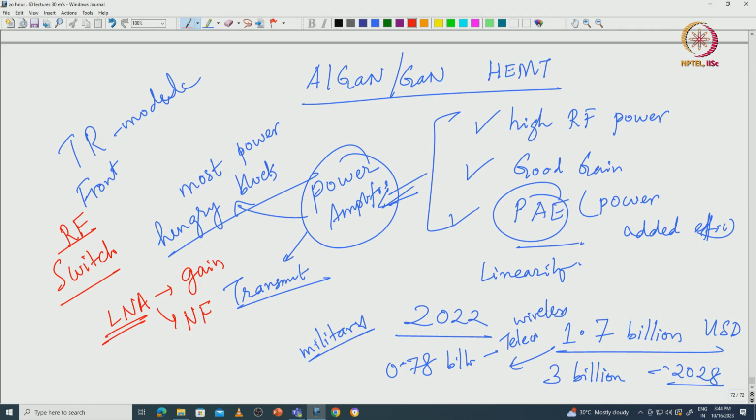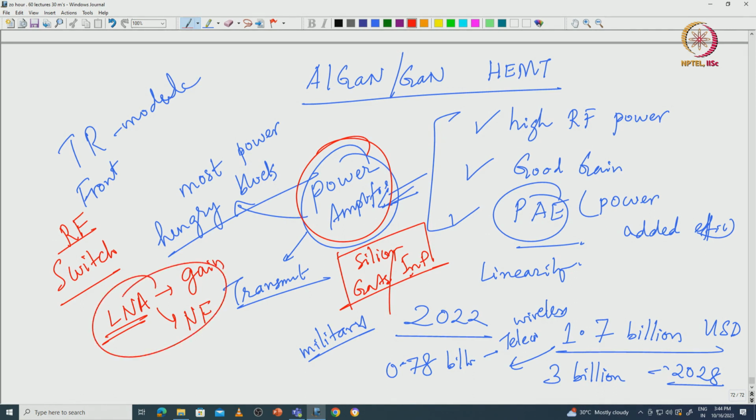People are looking at RF power amplifier in gallium nitride because gallium nitride can give you power densities that are not possible with other technologies. Okay, and when I say other technology, I mean silicon RF and I mean gallium arsenide or indium phosphide based RF. Those materials, it's impossible for them to match the power density that is provided by gallium nitride because of the superior material properties of gallium nitride. In LNA and in switch, gallium nitride may or may not have a superior advantage.